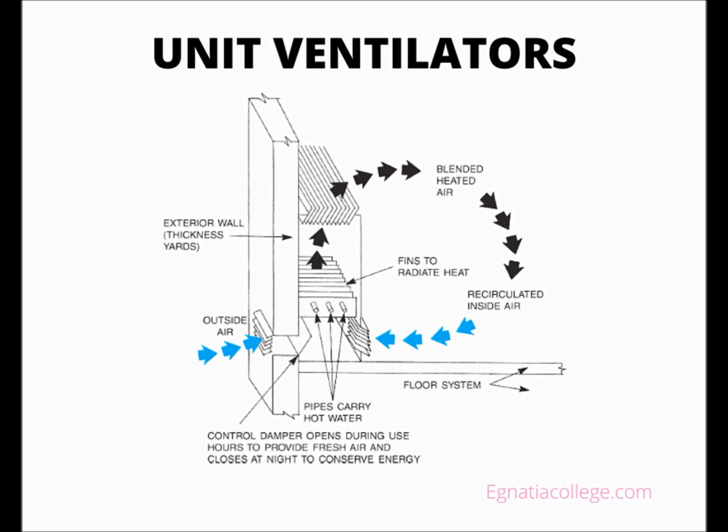The amount of air that is drawn in from the outside when the dampers are closed as much as possible is indicated on the drawings and on the schedule as CFM, cubic feet per minute. Other information on the schedule of unit ventilators describes such things as the total amount of air that passes through the unit, the water temperature intended by the designer, and the speed of the fan.